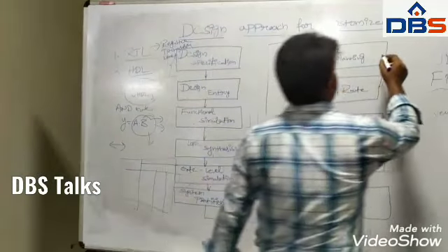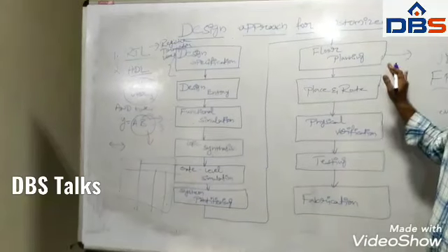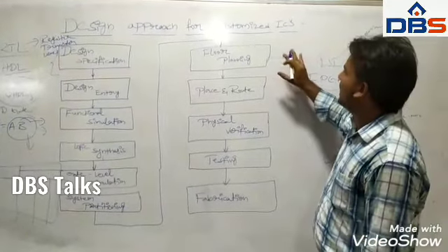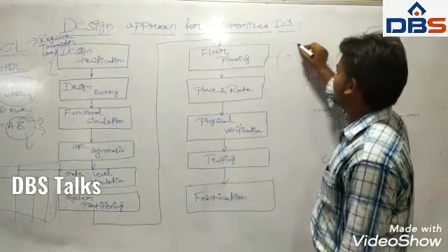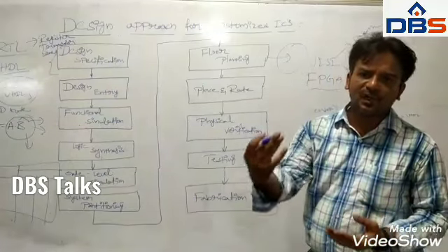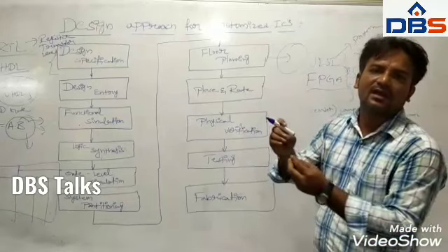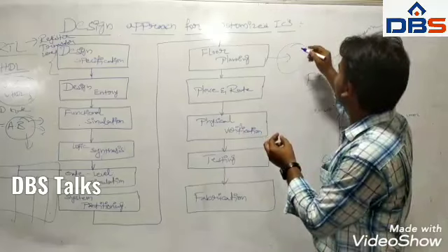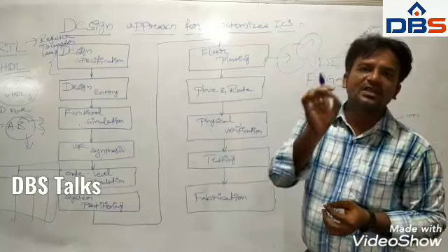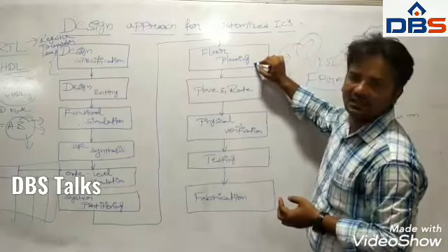After that division comes floor planning, which estimates the required chip area within the design. In a design we have inputs and outputs, registers, and memories. In what place we are planning, or how much space will be required for each and every individual subsection, that will be done in the floor plan.